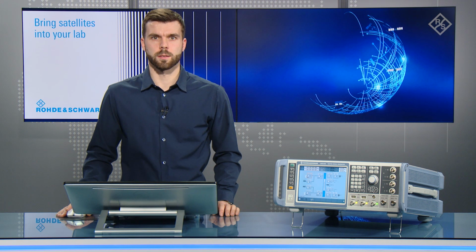This kind of testing is necessary to assure that a GNSS receiver works reliably in an environment where multiple other radio signals are present. Special care has to be taken when the GNSS receiver is integrated in one device with other transceivers. For example, a GNSS receiver in a smartphone is operated in the direct vicinity of transceivers in the GSM, EDGE, UMTS and LTE bands. These transceivers transmit with high power and might couple to the GNSS receiver. Also, mixing products and harmonics of these cellular signals fall directly into the GNSS L1 band.